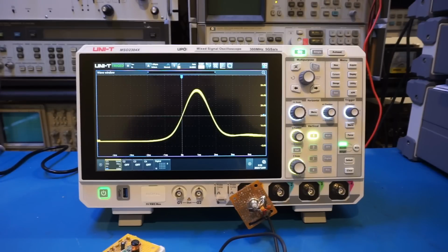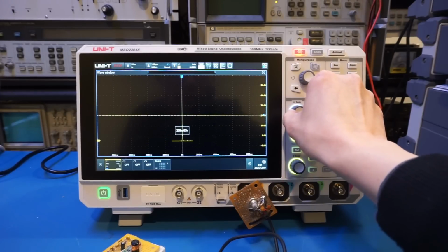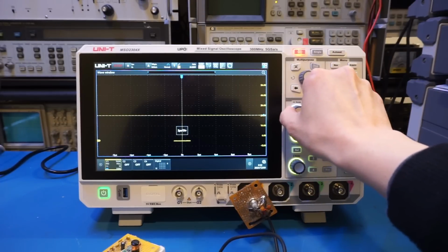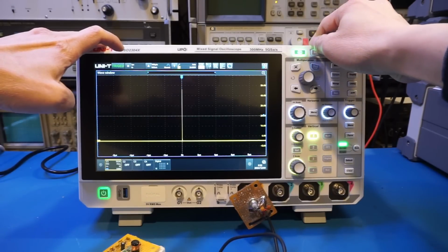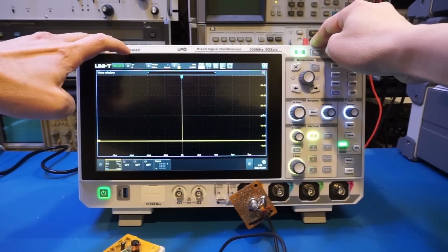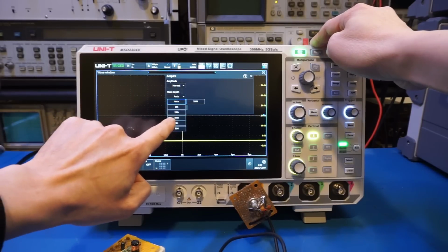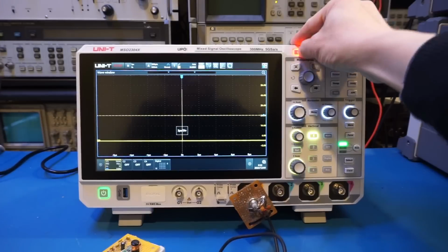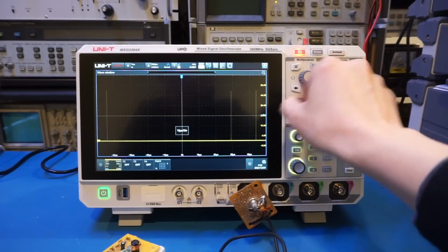And let me actually demonstrate this. Let me first stop the capture, and let's see how many we captured. It looks like we only captured one. Let's start again. Let's see how many. So let's increase the memory depth a little bit. Let's run, and let's come to acquisition. So the memory depth, let's change it to 250K. Let's run again. Stop. And we captured 2. Okay, let's run. Stop. We captured a few.